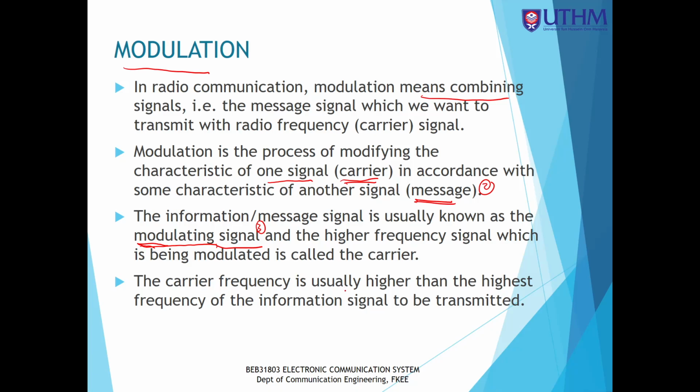So the carrier frequency is usually higher than the highest frequency of the information signal to be transmitted. The carrier signal has higher frequency compared to the highest frequency of my voice, because my voice is not a single frequency, it has a set of frequencies in a range. So the carrier signal must be higher than the highest message frequency.